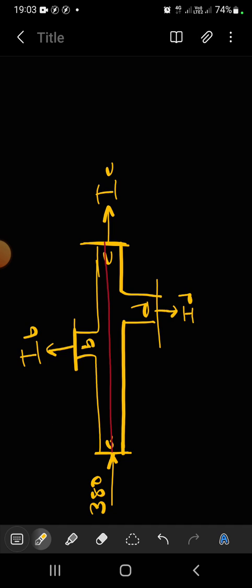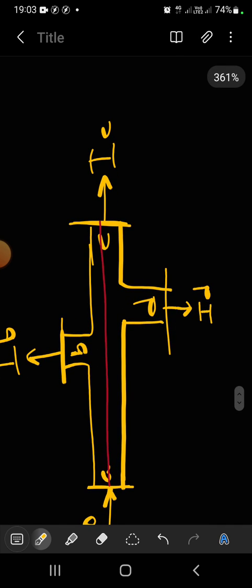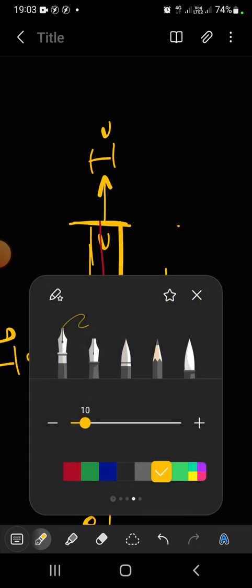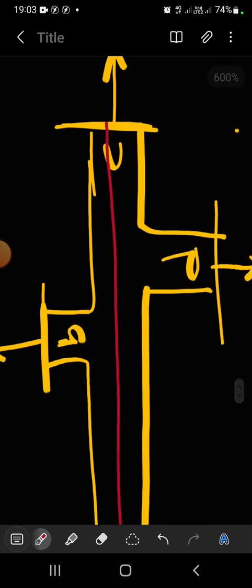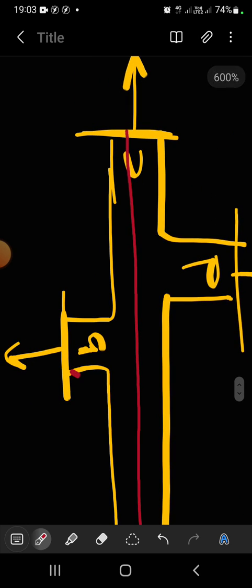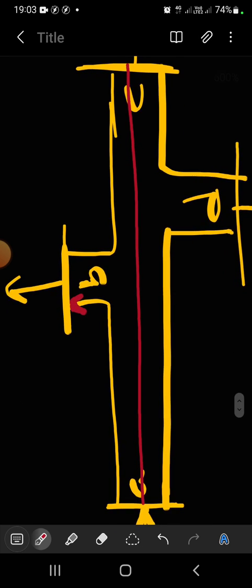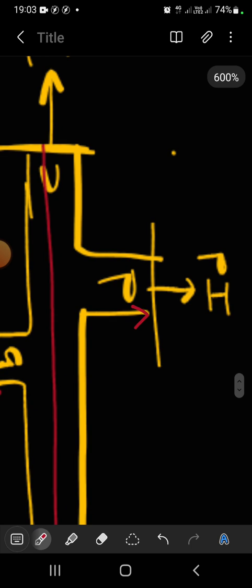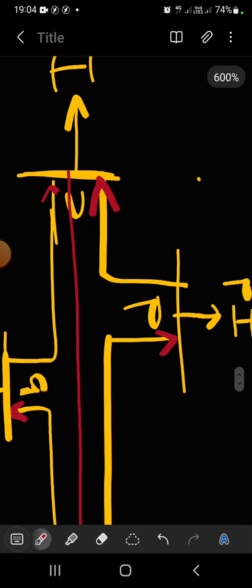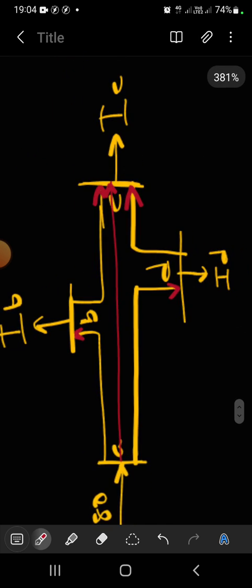Remember, the first step to AC problems is to always give your currents direction, assuming that your current flows from the supply all the way to the furthest point of the circuit. So we have that. That's the first thing we do. I'm not missing anything.